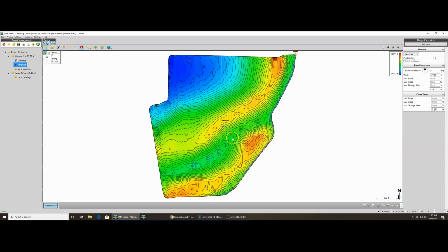Alright, now you see how these lines here have self-populated. Those are our rows essentially. Okay, we don't like them rows. We will put those rows downhill direction on 270 degrees, and now you see we have our rows generally covering the whole field. Right down here at the bottom we don't quite. So what we can do is drag our pipe down here to where we cover 90% of the field. This little area is real short, real narrow. Okay, so that's covering our whole field.